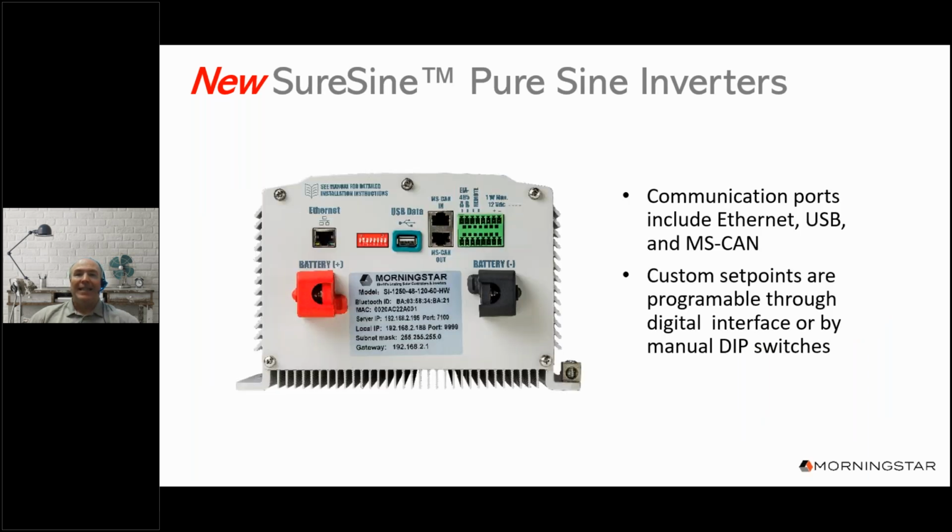And here you see the DC input end of the new SureSine inverter. In addition to the red and black positive and negative battery terminals, you see the communication ports that include Ethernet, USB, and MS CAN. As I mentioned before, you can customize inverter settings via manual dip switches or through a digital interface that you can access through Bluetooth.